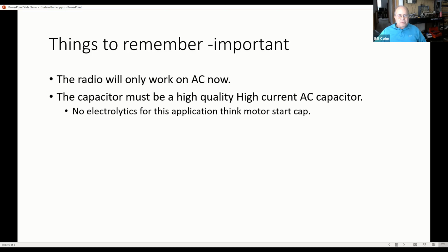The recommendation was made by one of the fellows on the internet. He actually made a bank of several of these, and you start at the low end, at 1 microfarad, and start switching up. You put your voltmeter across one of the 6-volt tubes in the chain and start cranking up the capacity until you're getting approximately 6 volts AC across that tube. And that will then give you the final value.